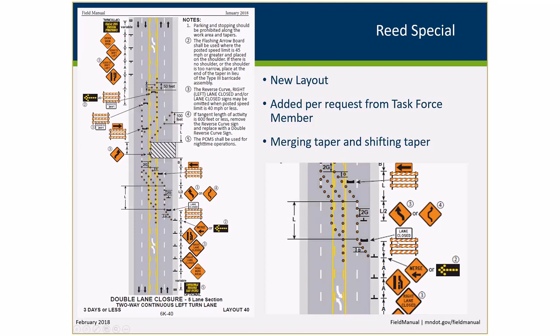But we wanted to put a lane closed sign on top of it, to provide more area for more signage for a person to see as they're approaching that. In addition, because that's a black and white regulatory sign, it really makes it clear that that lane is closed and drivers can't go into that area. So granted, we can't use a one direction large arrow anymore, but we feel that this is a good substitution for how we do our merging tapers.